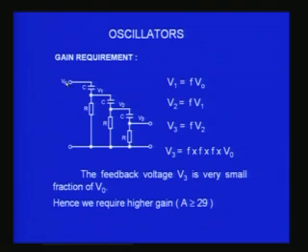So there will be a continuous reduction, and therefore you have to amplify this to bring it to some level so that A beta becomes equal to 1. Whatever reduction has happened here, you should amplify. If it is 8 times, you should amplify by 8, so that you get A beta equal to 1. That is the whole idea behind this phase shift oscillator. Here I call f the fraction of the output, not frequency.